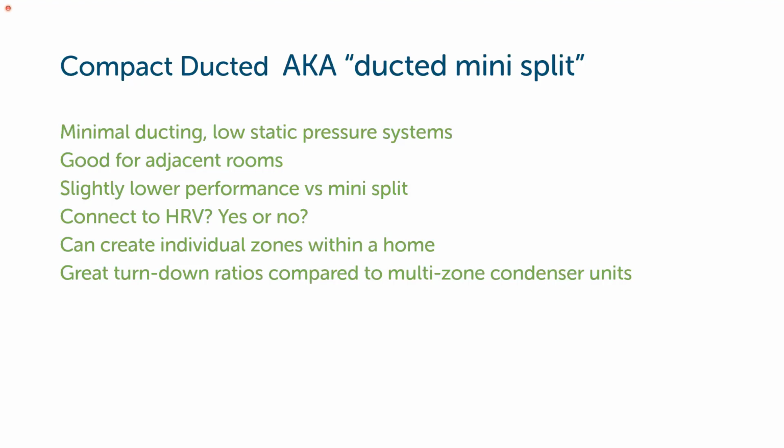So it's slightly lower performance than straight up mini splits. You can't beat the raw efficiency of a single head mini split, but single head mini splits aren't always the best option for small load rooms. And that's, again, going back to the design philosophy here, why it's important to know the room by room load calculations.